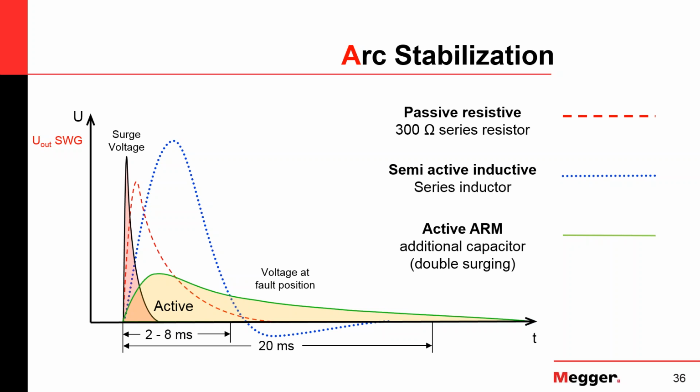Those are triggered TDRs. So now, if you think about it, the longer the cable gets, the more the runtime differences between the TDR pulse and the actual discharge of the high voltage source can become a problem. So the TDR has to be timed very precisely to actually hit the standing arc to reflect back.